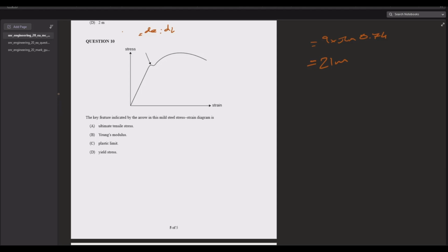This is just a general knowledge question, again. So, you should know a lot of things on your graph by this point. If you don't, you should really start considering to do that. So, this area is called strain hardening. And then the following area after the ultimate tensile strength point is going to be necking, because the material's pulling on itself, it's getting thinner just before it fractures. That's why it's called necking and fracturing. You get that?